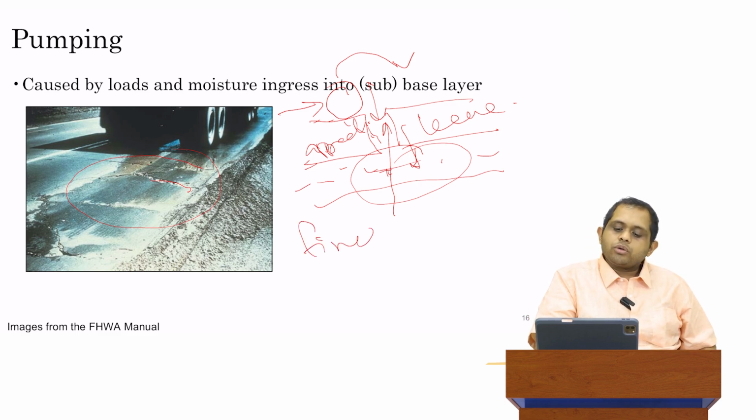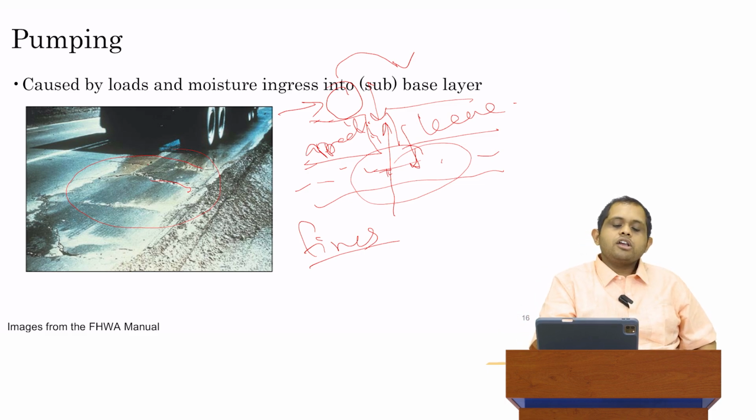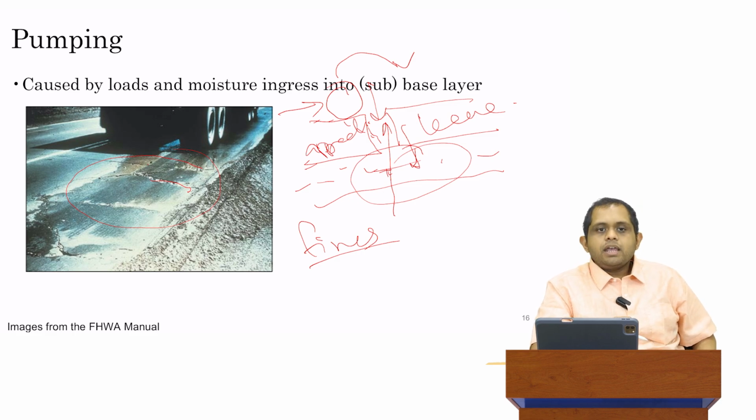Fine materials, what we just call fines, which are in the base layer or maybe even the subgrade layer if the moisture has gone deep enough, fine materials will also get ejected out. Eventually, at the end of the day, what you will see is your road is covered in muddy, dirty water.